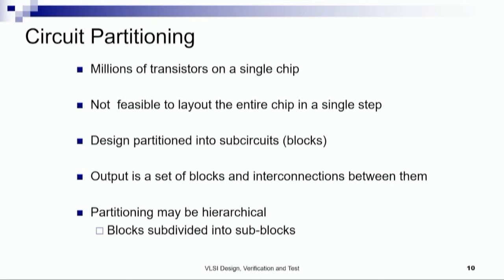Welcome. The physical design process is divided into many sub-steps. The first sub-step among them is circuit partitioning. So we said that at the end of the logic design step, we will have a circuit design consisting of millions of cells, macros, gates, transistors and their interconnection. Now, we have to place this entire circuit design into a single chip.